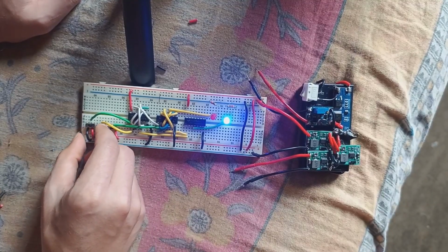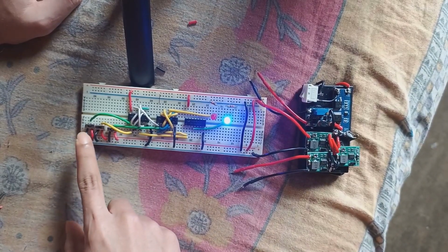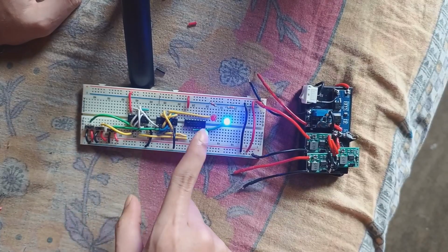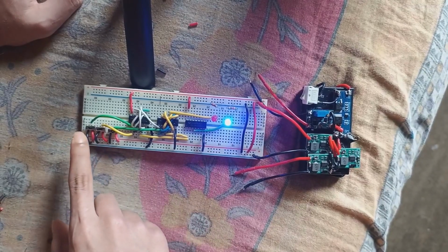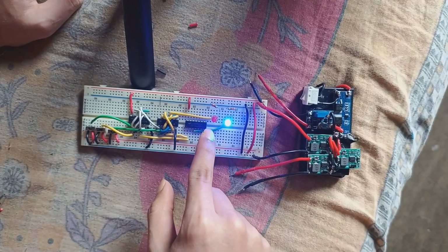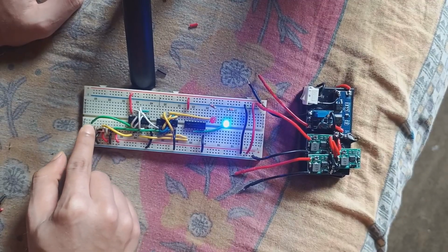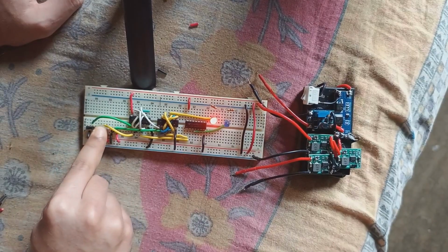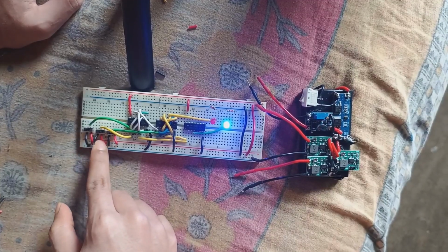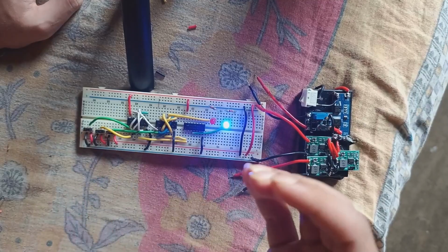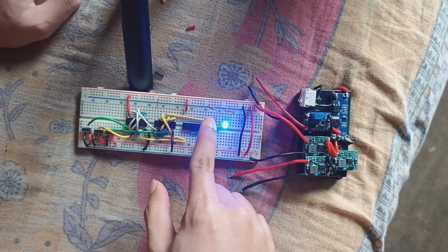Let's turn B off and give the carry 1. Where A is 1 and carry is 1, the output is also the desired output. Sum is 0, carry is 1, because 1 plus 0 plus 1 is sum 0, carry 1. Now turn A off and turn B on, and this is also the same, 0 1 1. So 1 plus 1 is 0, sum 0, carry 1, and the other variable is 0, so it does not matter. Again sum 0, carry 1.